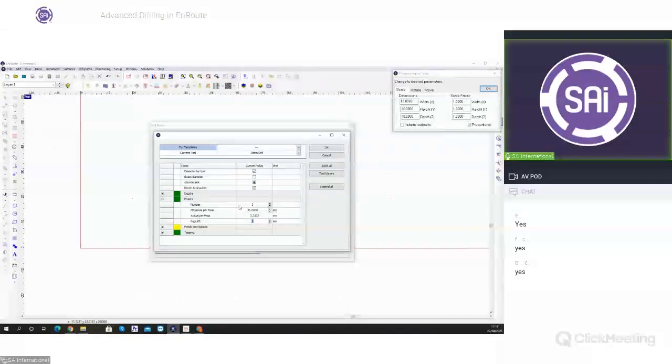So let's say here we'll go per pass to a depth of 3.3. If we set this to 1, it will, for each pass, go 3.3 into the material and then lift up 1mm. Or, of course, if you have fewer passes, for example, you can set this to 3. And you can use this one to clear out chips of the material without having to lift the tool completely out of the material again.